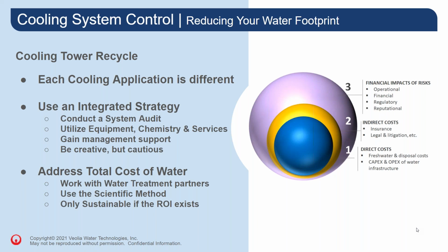First and foremost, conduct a thorough system audit and understand the use of the cooling water, the equipment that uses the cooling water, how it exchanges heat, whether it's operating properly under the current conditions, how it's performing across the entire system, and any areas of concern that you need to be aware of if the cooling water quality has changed.